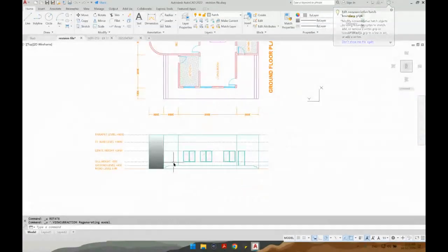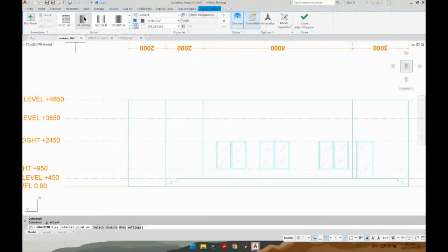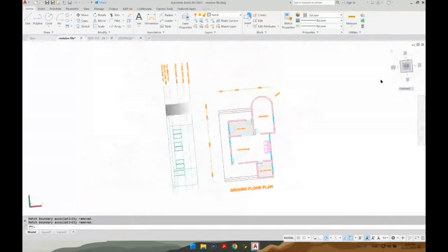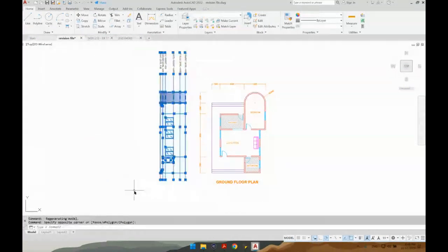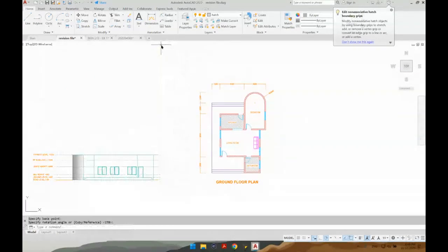Okay, again, so for the hatch, I will go to gradient, select gradient, linear, select the colors. I want the darker part for the far point, which is this one. And then the near point, I want it to be light, so I will keep it as white. And then I can click here to add my hatch. When I'm done, I will rotate my drawing again, select this one, rotate it, and you will see that the hatching is now correct.